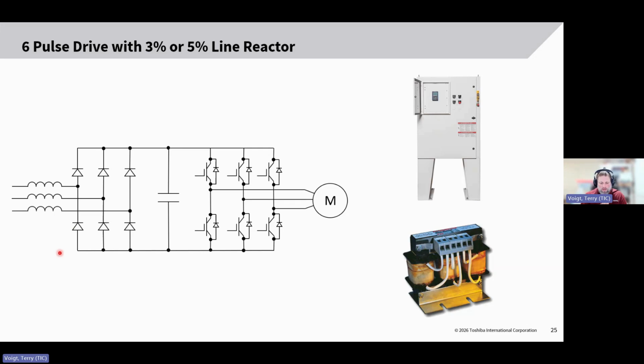I think the question was more on would we recommend a line reactor with a WC1? For harmonic mitigation, it's not needed. I don't think that's needed by any means, just because the harmonics are extremely less. For voltage transients, I think it has some plausibility. I don't know that I would recommend it every single time.